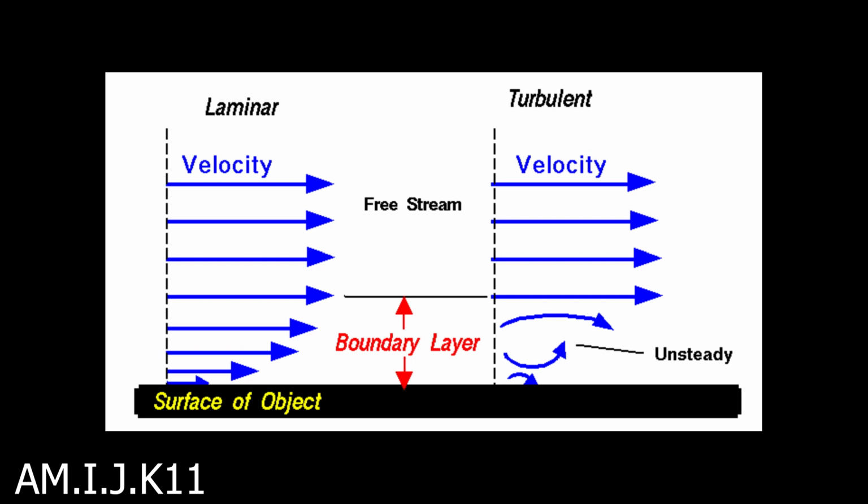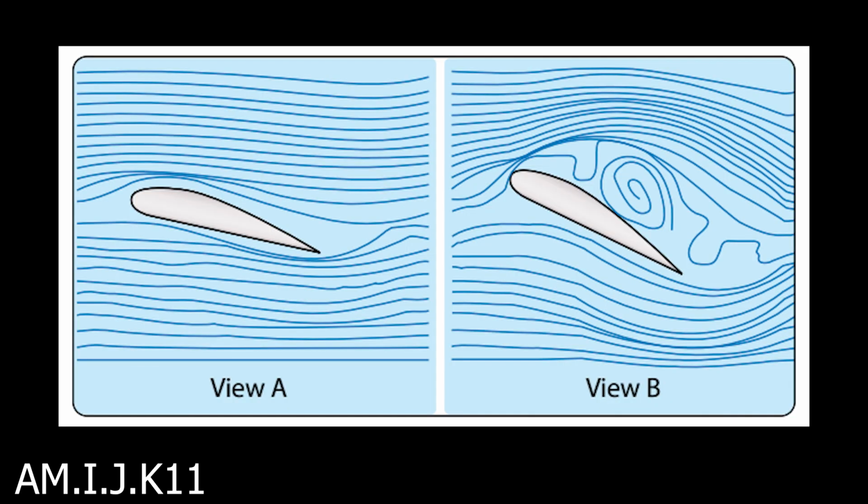Boundary layer airflow plays a crucial role in how aircraft wings perform. This thin layer of air adheres to the wing's surface due to air viscosity. As the wing moves forward, the boundary layer starts off as a smooth, laminar flow over the streamlined airfoil shape. However, as the air travels toward the center of the wing, it loses speed due to skin friction, thickens, and becomes turbulent, known as the turbulent layer. This transition from laminar to turbulent is called the transition point.